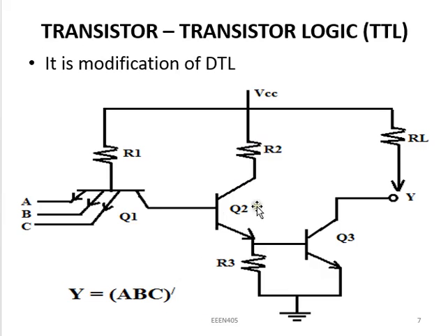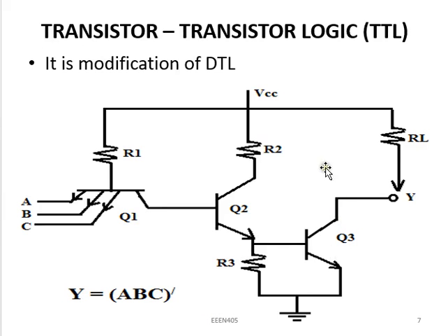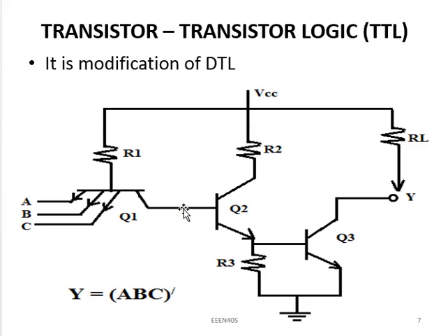And if you come to the second transistor, between the base and the emitter we have another diode, which is standing for diode D2. And finally, this transistor Q3 is working as my active transistor Q1 here. So if you understand this, the procedure, the operation of this one and this are all the same. This is also a NAND gate.